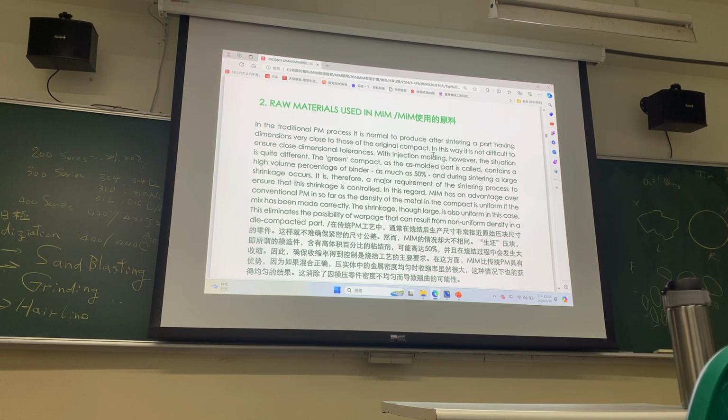Why? Because the density becomes high. When you tap this one, this powder will jump up and jump down, and the force will make every piece of rice straight. So they can arrange closely very well. So we use this concept in the MIM process, and then finally found the powder shape is like a potato, which can get good density.